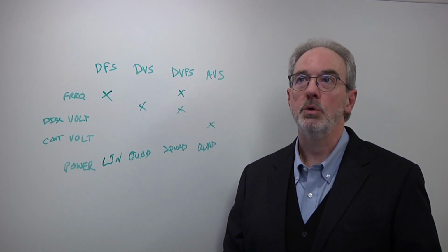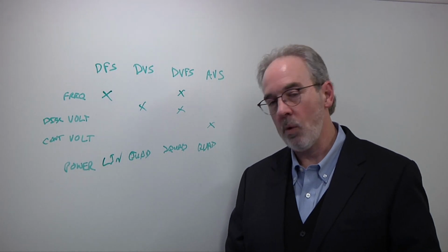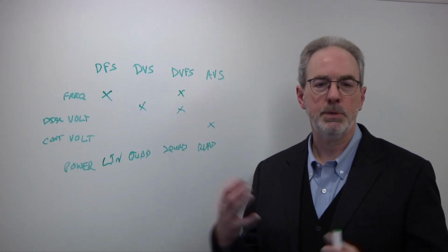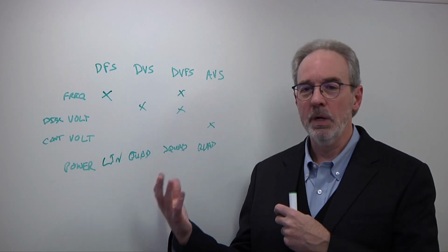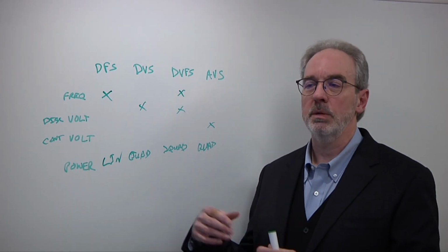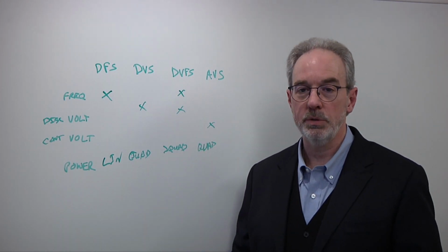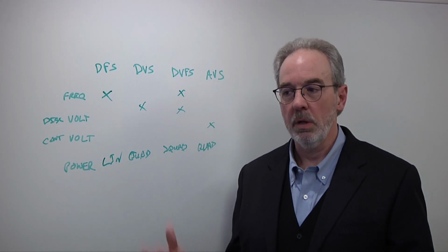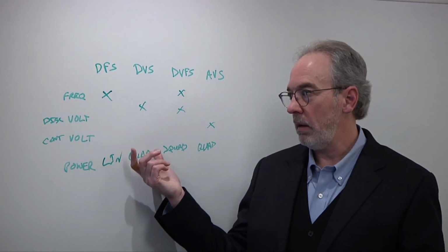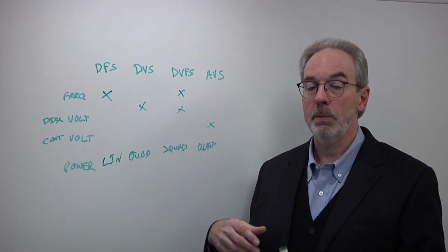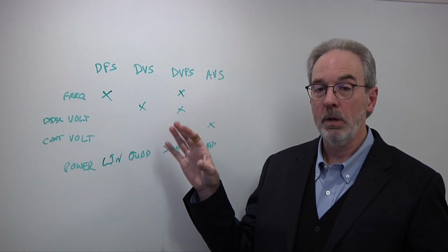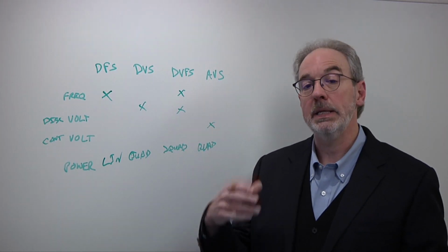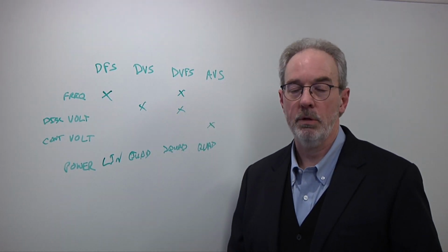That's absolutely true. And in fact, I would argue that the power grid design of a modern SoC, especially a larger design, is an incredibly complicated endeavor because of the demands of chiplets, the scale of the designs, the modularity, the rapidly changing workloads. It creates a very hostile environment. So having the ability to create this localized control, having the ability to isolate certain regions with power islands in a simple manner, as opposed to some of the more complicated techniques, is an enabler that drives this technology forward.